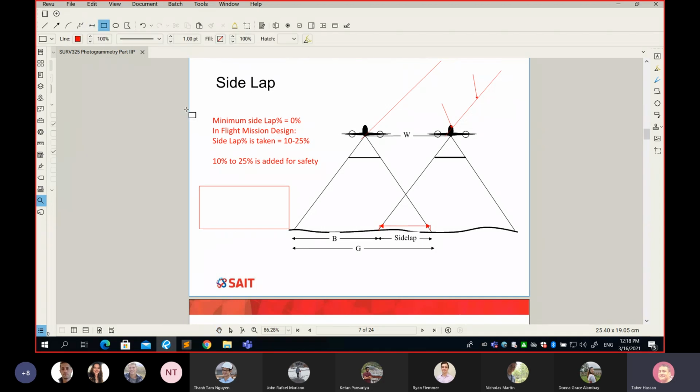Okay, so as I said, let's say, for example, my images are like this. So, okay, I have one image, I have another image, and this is simply how much every image covered on the ground. And you can see we have overlap in between them. Okay, like so. My point, which I'm trying to make, is that if I maintain zero overlap, so you're just touching each other, maybe if I'm pushed by the air, maybe my image will become this way, and my next image will go this way.